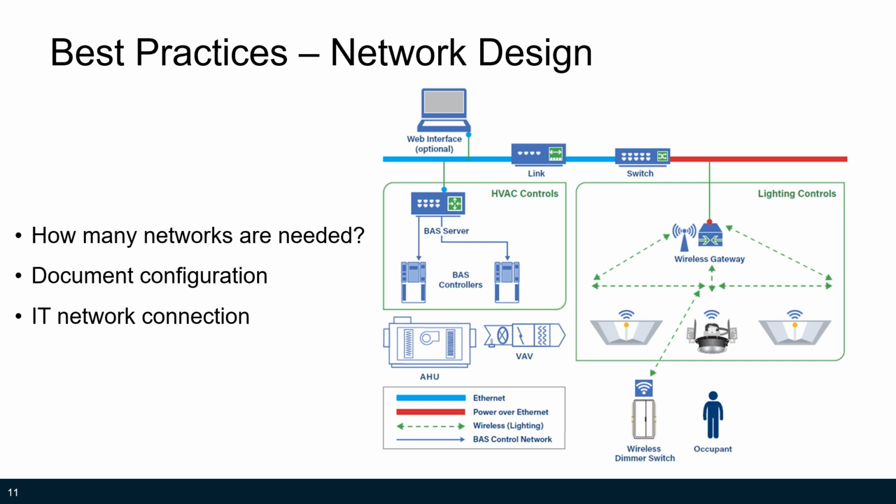Within the design phase, some additional effort is needed to plan networking components and configuration. Whether the majority of the lighting control system is wireless or wired, some wired networking will be necessary for the integration. The electrical contractor takes the lead on this, with help from the manufacturer's sales rep. The networks can be very simple, but some forethought is still needed.